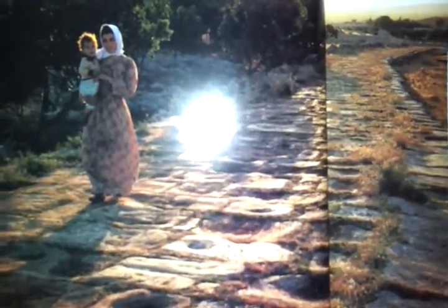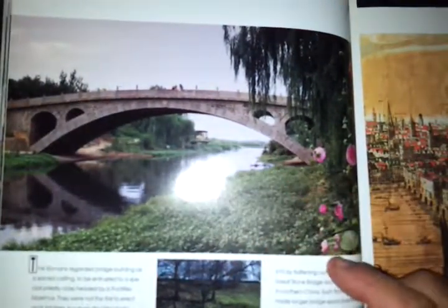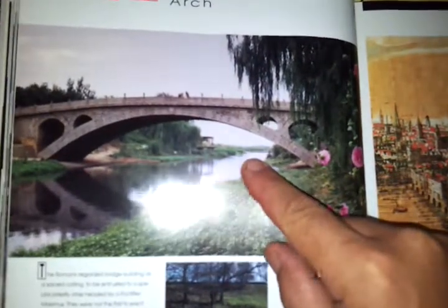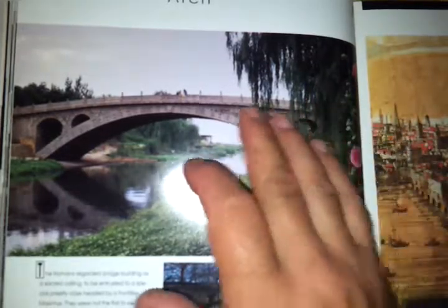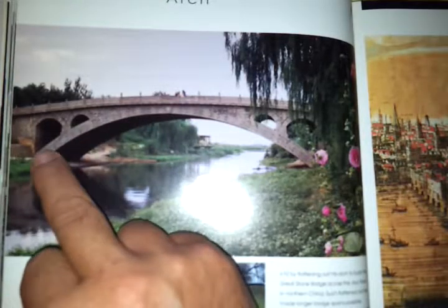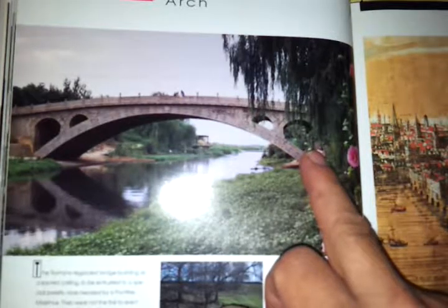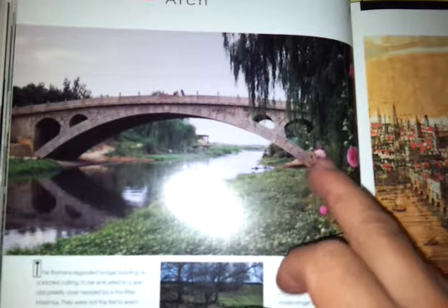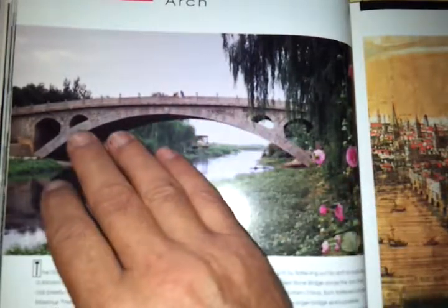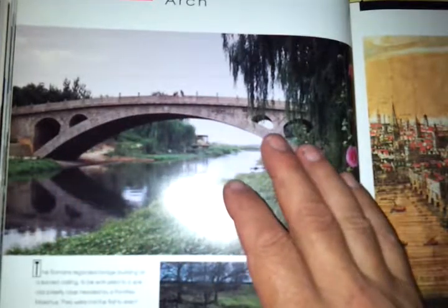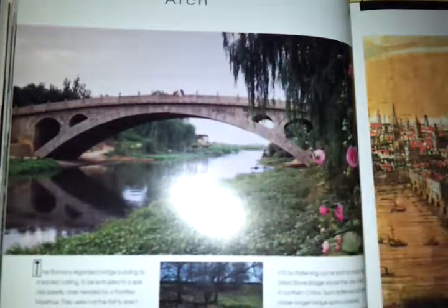Okay, other sorts of structures that have been used. We can see bridges. An example here of a beautiful looking bridge with an extended arch made in China about 650 AD. So again, the use of stone with its strong compressive strength, and its plentiful abundance around the earth and around most countries. Its use in civil structures has been for structures that need to be permanent and long wearing, at the same time have firm foundations and can take the weight, and also structures designed so as to put the stone in compression rather than in tension, because stone is very weak in tension.